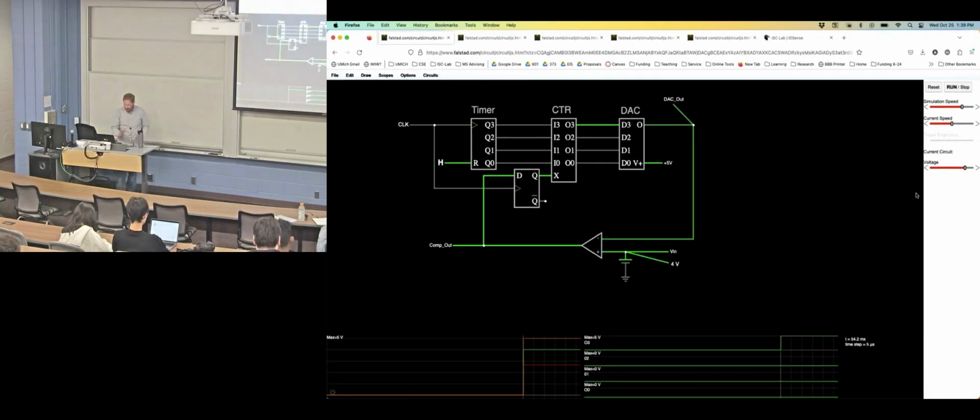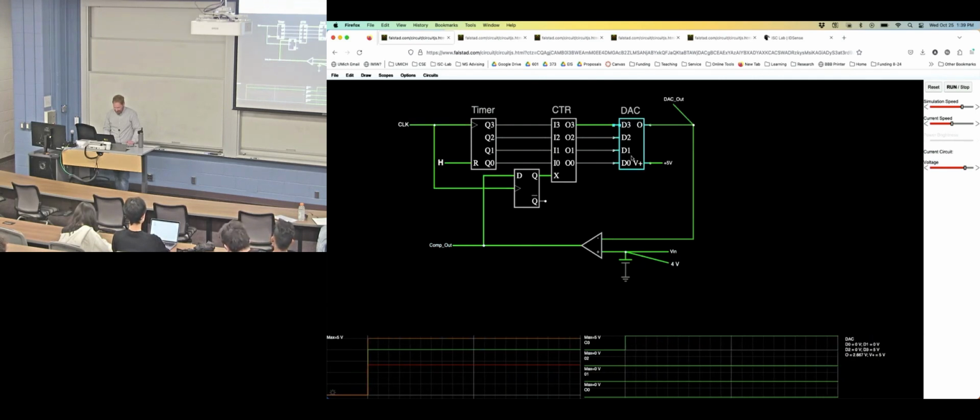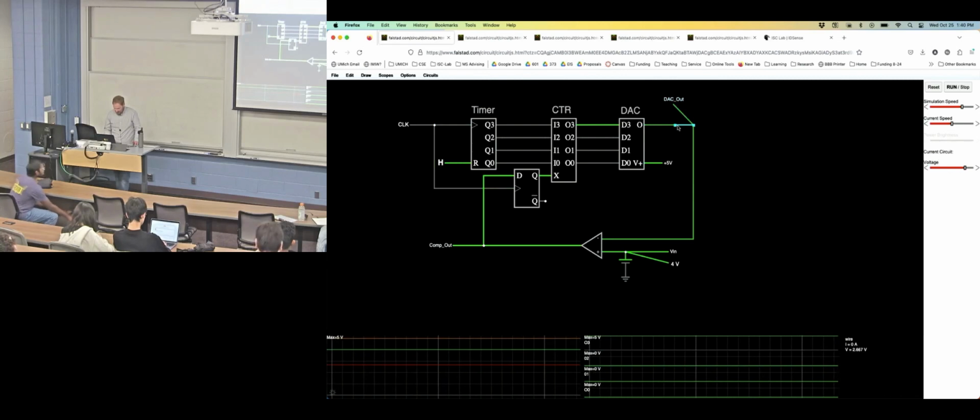All right, so in this simulation, we have an input. This is what we're comparing to, the output of the comparator. This is our DAC, a digital to analog converter. Again, we haven't talked about how that works. We're just going to assume for right now that it is smaller than an alternative, like a large resistor ladder, so we're trying to save some space. Okay, so that's going to put an analog voltage out here.